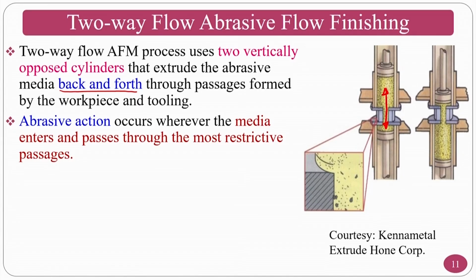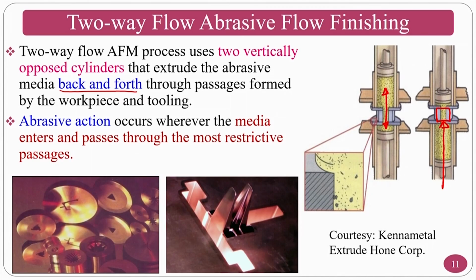If you see in this picture, the most restrictive passage is this particular part. This is the most restrictive region, because of which the medium experiences more restriction. That means the abrasives will abrade more in that particular area. The common type of workpieces finished using this are through holes. In the previous case you can go for through holes in a wall or some other places.